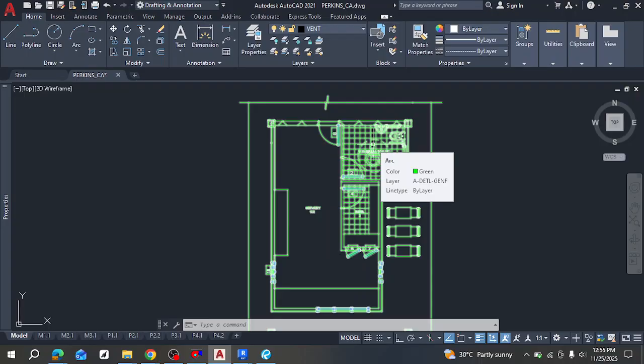So that value is usually more accurate than what you have here. Sometimes it's close. Sometimes the total sizing is 1 ton and the other one is also giving the same thing, but in some cases it's not. In the case where you have to select, you pick this. So in this case I'm going to design with that 36,000, which is 3 tons.